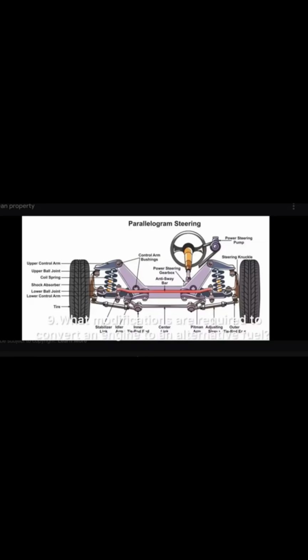9. What modifications are required to convert an engine to an alternative fuel? Fuel delivery, fuel storage. The engine needs to withstand the fuel. LPG needs harder valve seats. 10. What is the purpose of forced induction? Improve volumetric efficiency. 201B engine blocks.